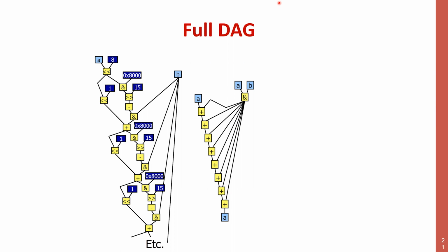There is an adder that is called a carry save adder. That is a very funny type of adder because it takes 3 words to add and returns 2 words whose addition is the same value as the addition of the first 3.